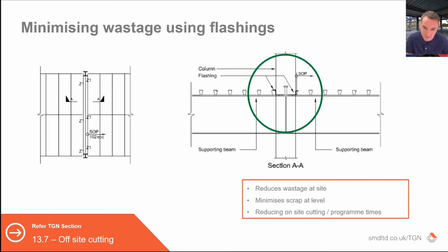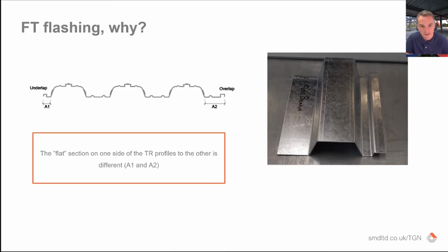So we're talking about flashings. We've already done that. But that has led us on to develop other flashings. We've developed one we call FT. It's essentially a small trapezoid edge flashing to stiffen the flashing at the edge. You can see an image of it there. It's press brake flashing. SEI have developed that on our behalf.